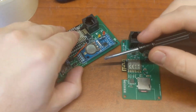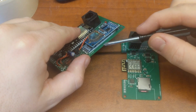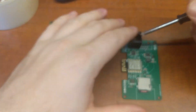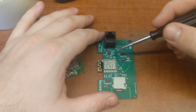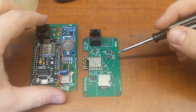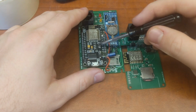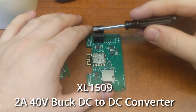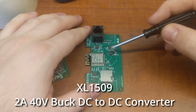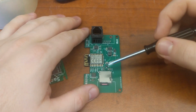And here we have the converter from RS232 or RS485. And on the new board, it's right here. So it's surface mount. And the other thing that changed is before this was powered with a linear power supply, but on the new board we have a switching power supply here that converts whatever is coming in here to 3.3 volts for this guy, because everything here runs on 3.3 volts.